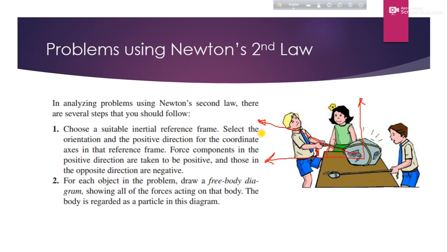So we need to decompose the force. We need to find out the components of the force. One component will be acting this side and another component will be acting this side. We know that if the force is F, this is F cos theta, and this side F sin theta will be acting. So we need to decompose the forces this way.